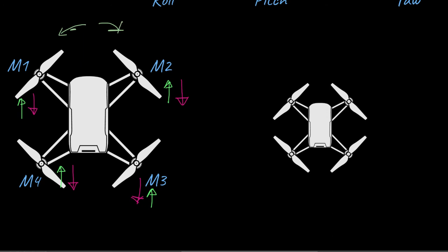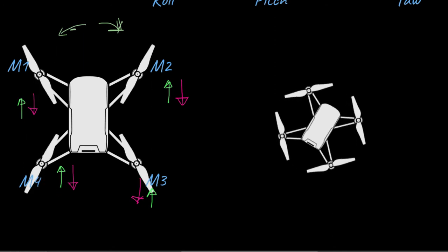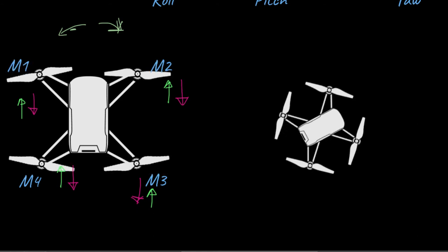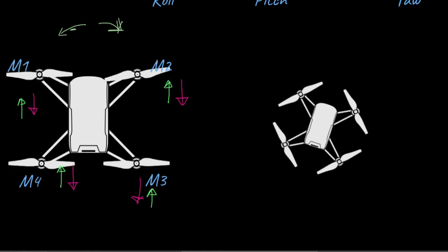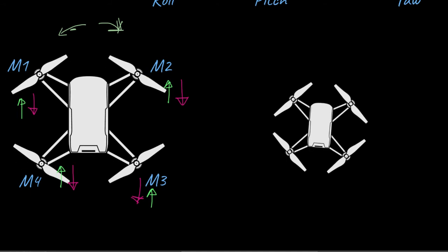So to prevent the rotational force, we need to counteract that, and that's the reason why we have propellers in different directions. So this is how it would work. If you wanted to move in one direction, the propeller that is moving in the anti-clockwise direction will need to be at a higher speed than the propellers moving in the clockwise direction, and that's how you can make the quadcopter move anti-clockwise and vice versa.